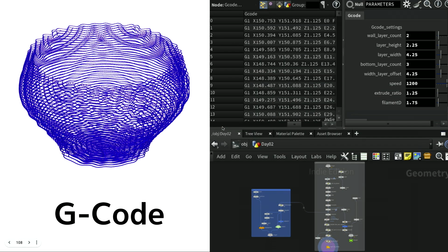Once you have this analysis, we convert the curve data into G-code by applying the position of each point as X, Y, and Z coordinates, as well as speed and the amount of clay volume that should be extruded based on the whole material size.